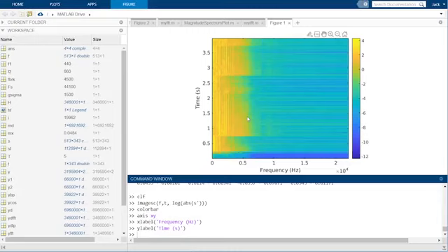So what is shown is the magnitude of the frequency content for each frequency in the signal on the x-axis as a function of time on the y-axis. Each horizontal line in the plot corresponds to one 25 millisecond time window, where colors shown on that horizontal line are akin to the height of our 2D magnitude spectrum plots. So instead of having one magnitude spectrum plot for the entire signal, the spectrogram generates individual plots for small time windows.